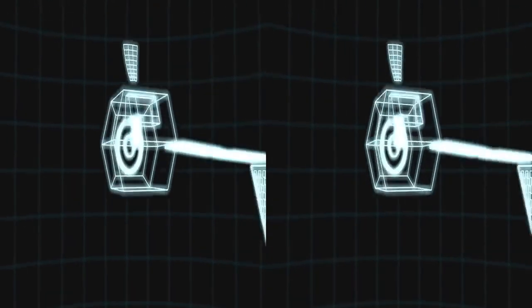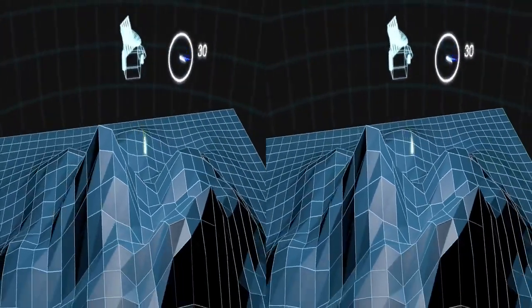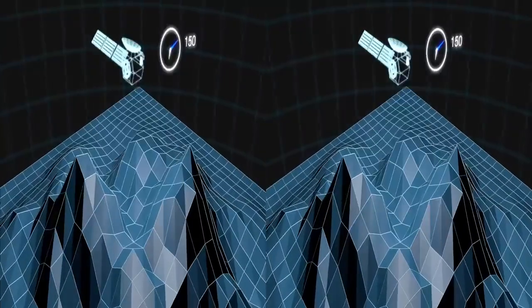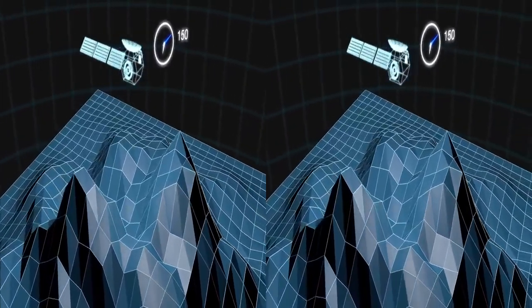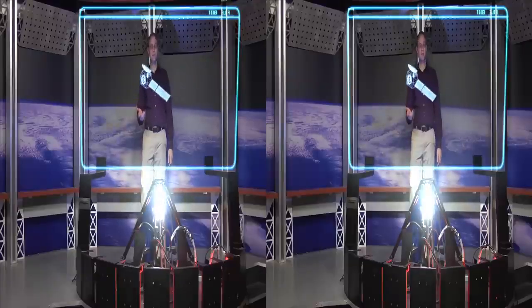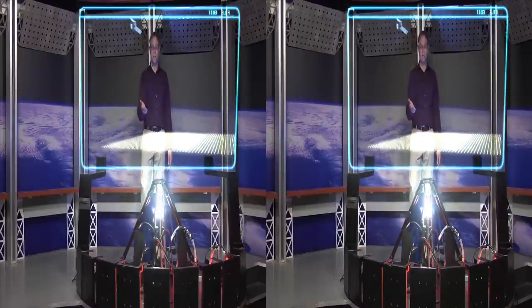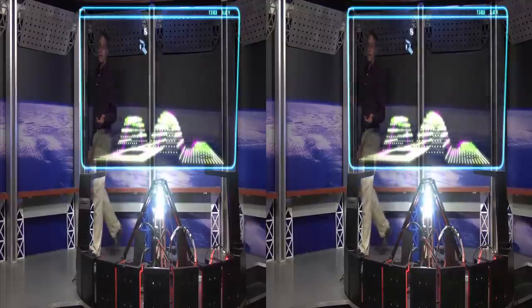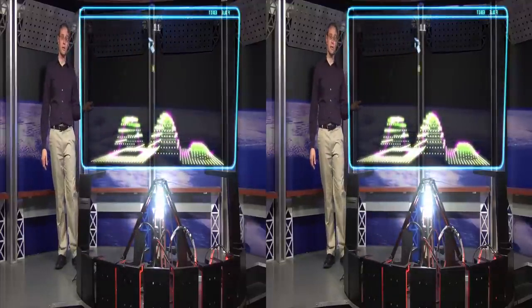To make these measurements, the LIDAR instrument first sends a laser pulse down to the planet's surface. The pulse hits the ground and reflects back to the instrument, where an onboard counter measures the time it took the pulse to make its trip. That gives a precise measurement of the distance between the instrument and the ground with respect to the planet's gravitational center. As the satellite passes over the landscape, the instrument sends out a series of regular pulses.